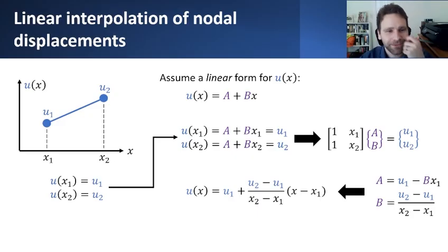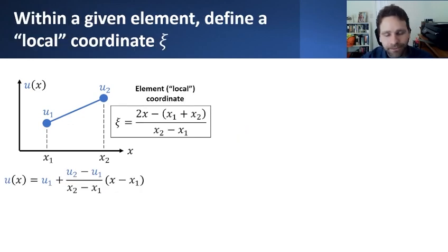So that's really the simplest way that you can rationalize how you come up with these interpolating functions, functions that pass through these discrete values assigned at discrete nodal locations. So with that, I could represent everything in terms of how I showed on the previous slide. I've reproduced it here below this figure on the left, showing what the explicit representation for this function, the displacement field, is as a function of spatial coordinate x, where x is expressed in terms of the nodal positions also.